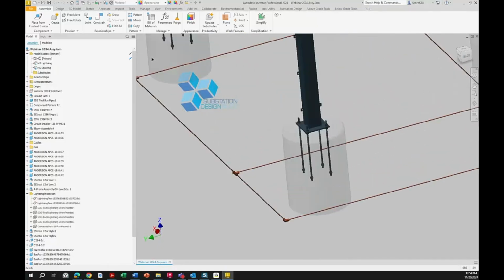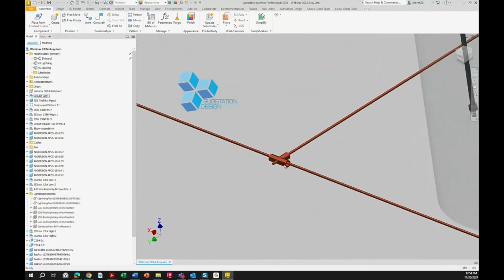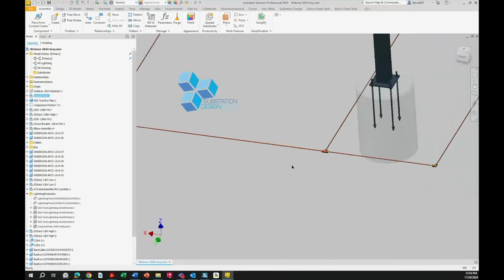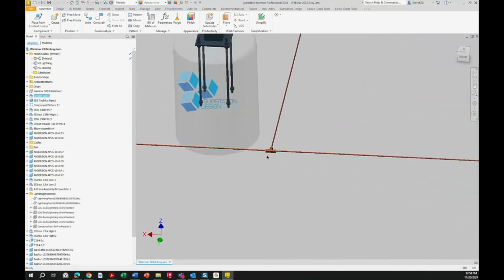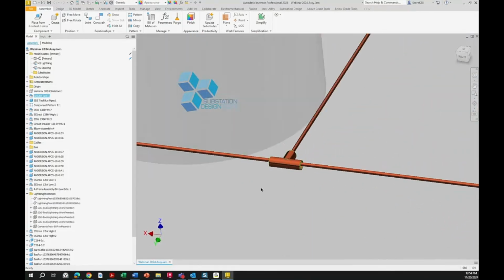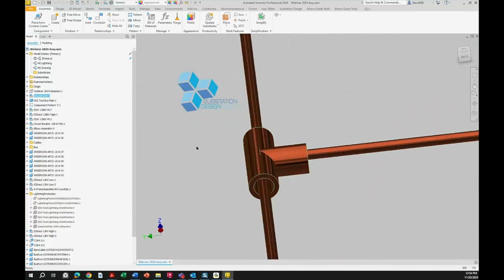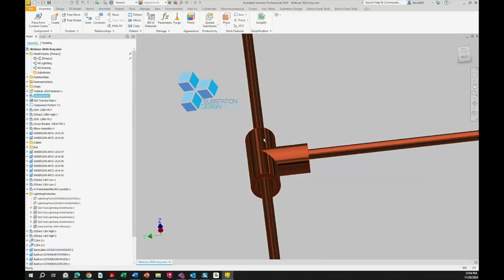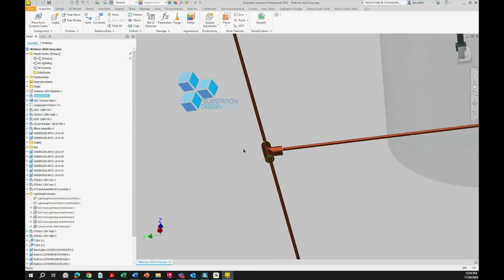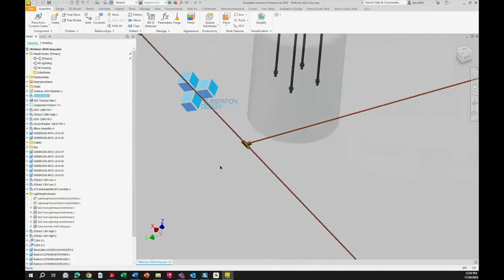And what I have here are my T connectors, right? So you can see the T connectors in here. I know a lot of people are using a cross. The true cross has the branches at different elevations. SDS is not set to do different elevations. And with a ground grid, it's not a huge concern because it is buried the way it's done. So I made it all on one elevation.